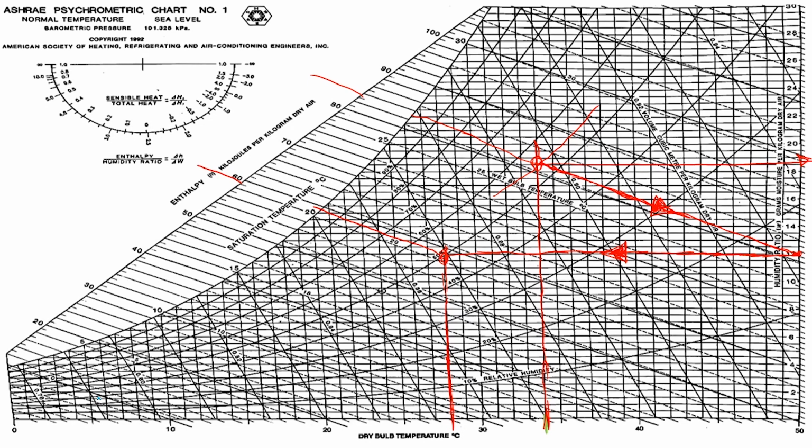For the second system, we have conventional cooling with compression refrigeration. The coil dew point is 15 degrees Celsius, so we just connect the ambient and the dew point. Since the coil efficiency is not 100%, the outlet will be higher than the dew point. We assume that the coil outlet is the heater inlet, so the heater will follow the same horizontal line to the room inlet. The heater line will cross the coil line at the coil outlet and heater inlet point, so we take the enthalpy data from this point.